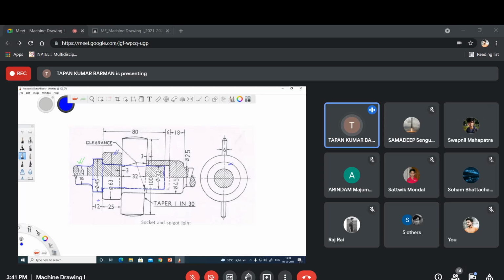That is the reason some person asked earlier why we should put this edge. Originally, we have to make one phantom line for this. Yes, sir. Absolutely. Understand? Yes, sir. So this should be the projection view for this left hand side component. Also, at this position for this left hand side component, you have to put this dashed line. Here also you need to put the dashed line to show that there is a slot which will accommodate this third component. Is it clear? Yes, sir.